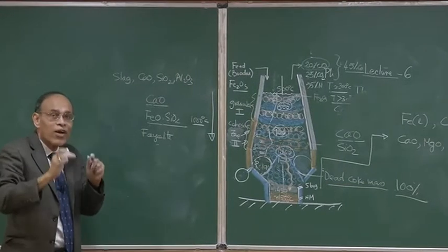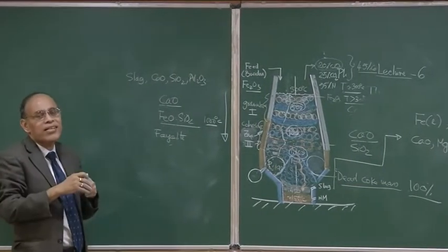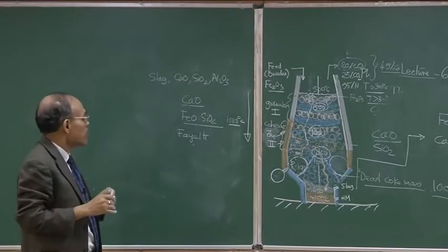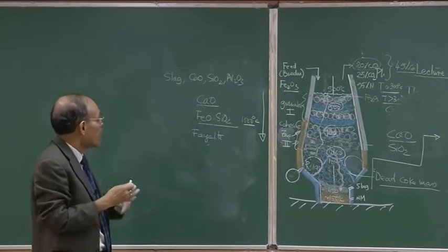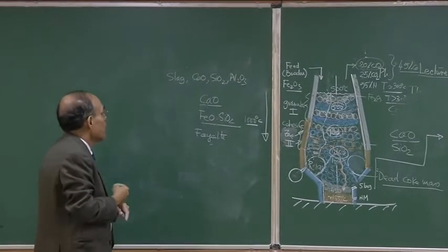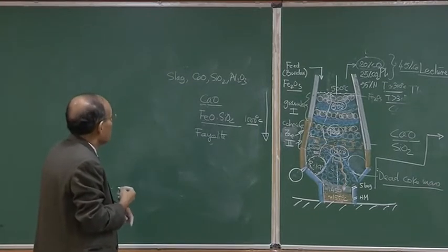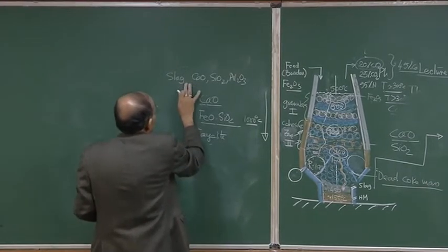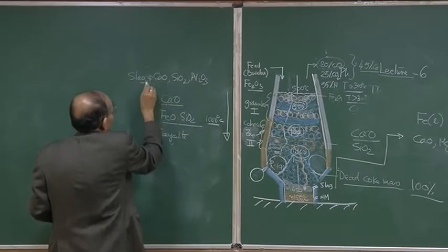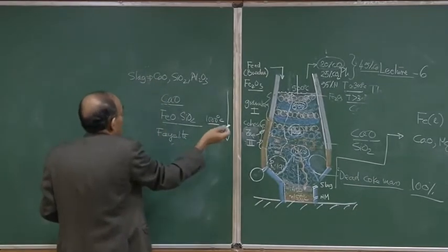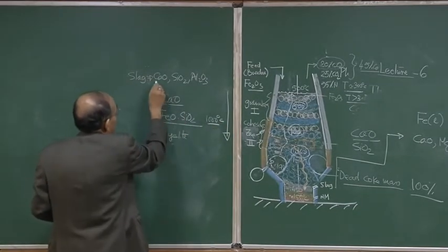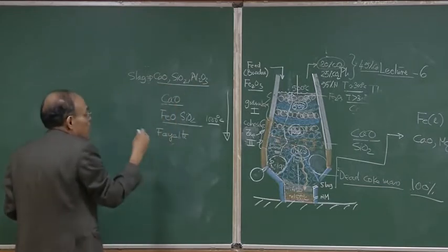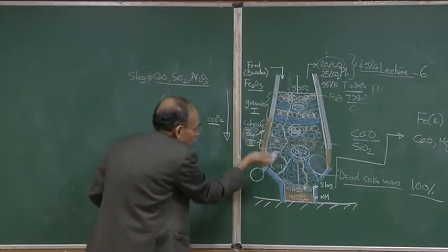All has been converted, because by 900 degrees centigrade, reduction of iron ore in an atmosphere containing CO is almost complete. So, the slag below the cohesive zone will contain, with progressive replacement of FeO, the silica matrix, as well as the oxides that are being taken up.